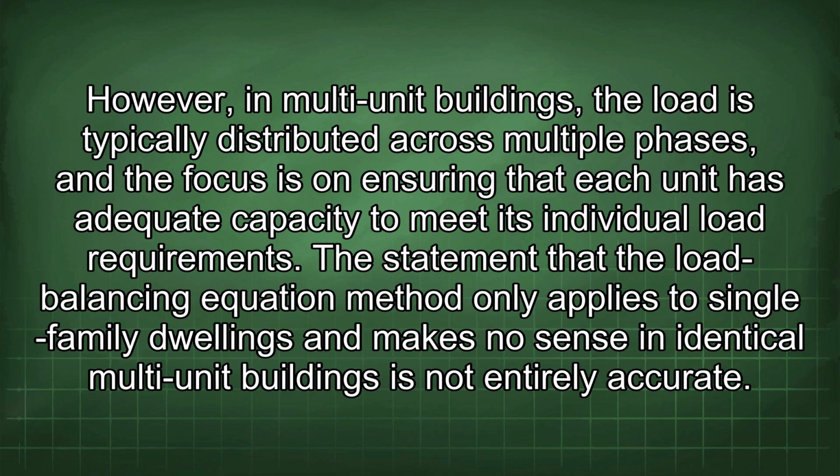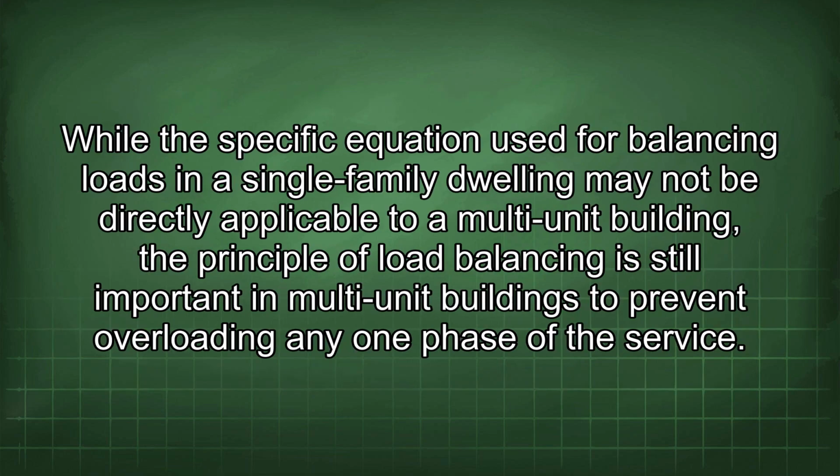The statement that the load balancing equation method only applies to single-family dwellings and makes no sense in identical multi-unit buildings is not entirely accurate. While the specific equation used for balancing loads in a single-family dwelling may not be directly applicable to a multi-unit building, the principle of load balancing is still important in multi-unit buildings to prevent overloading any one phase of the service.